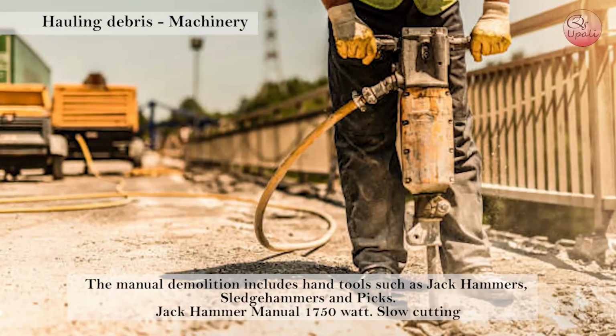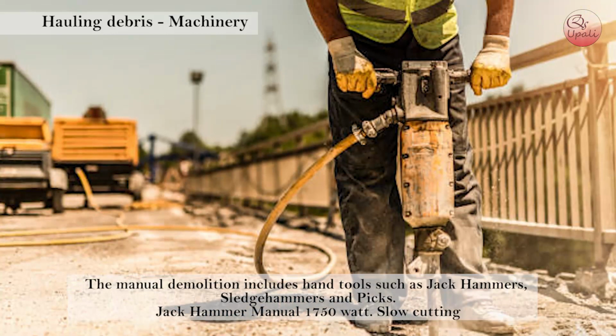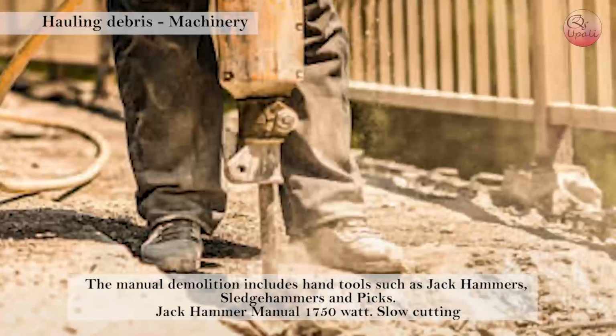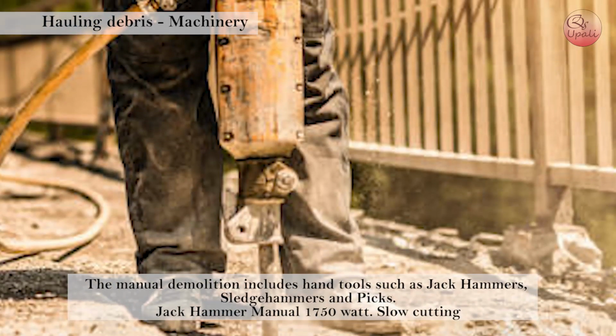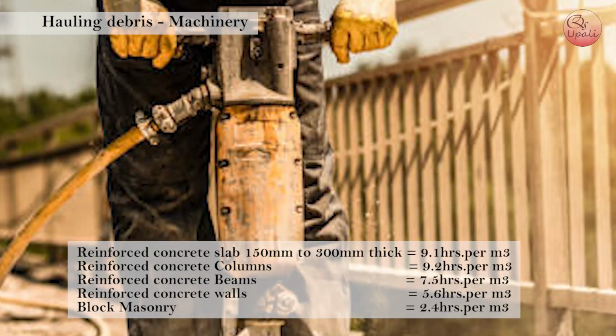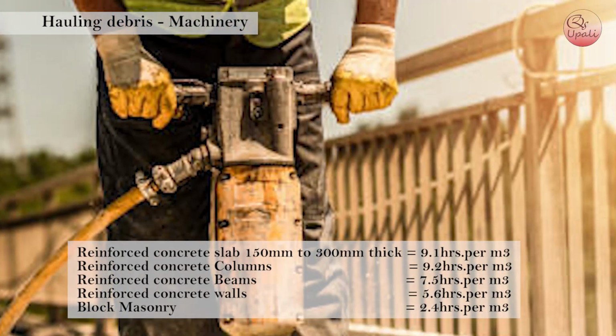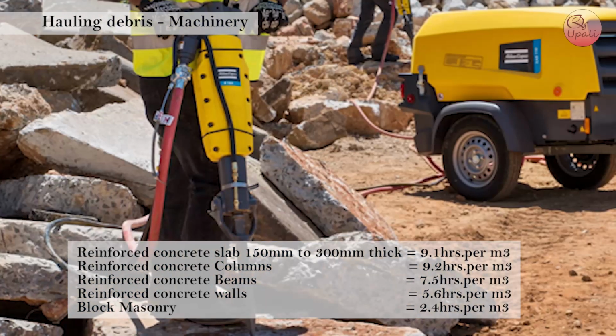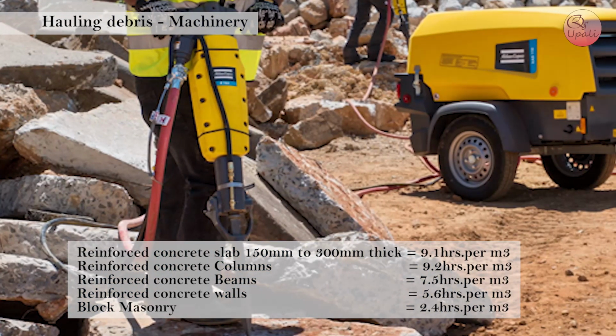The manual demolition includes hand tools such as jackhammers, sledgehammers and picks. Jackhammers, manual, 1750 watt, slow cutting. Reinforced concrete slab 150 mm and 300 mm thick, 9.1 hours per 1 cubic meter.